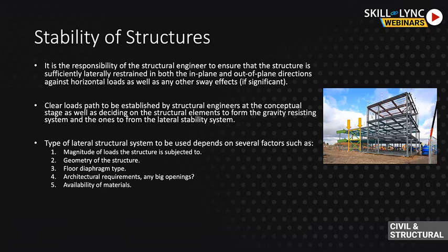So the orange part would be your gravity system, and basically whenever the load is applied on the roof, it gets distributed to the beam according to its tributary width, and then that goes as uniformly distributed loads that get resolved into reactions and then go as axial forces in your columns all the way down to the foundation to be resisted by the earth.